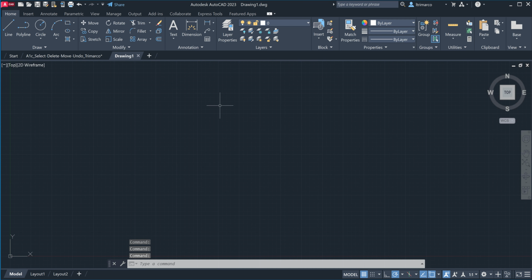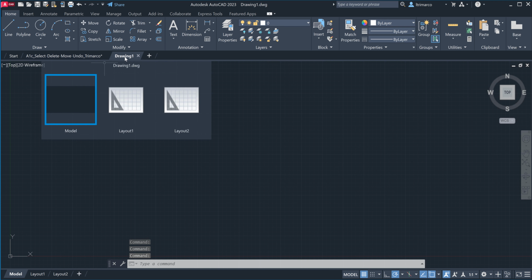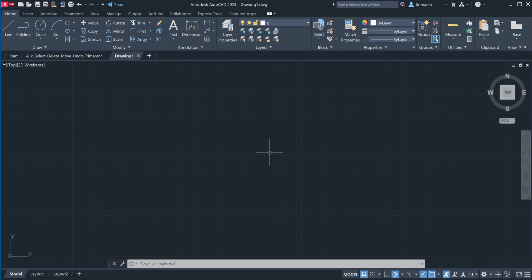And right away, we see the tab is named just Drawing 1, so I'm going to do a Save As very shortly. If I zoom out, on the bottom of my interface I do have the grid on. So as I zoom out, you should see a grid vertically and horizontally. You will see this user coordinate icon. Because again, what are we drawing in the viewport? We're drawing basically on top of a coordinate system called the world coordinate system.